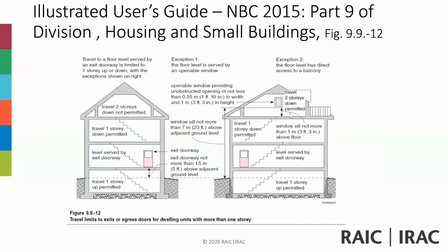The window openings requirement provisions related to that. You are always permitted one story of travel, one up or down, to get to a floor level leading to an exit. If you want to use these provisions, there are definitely provisions in the building code related to egress from dwellings. And Beryoska, you have a question.